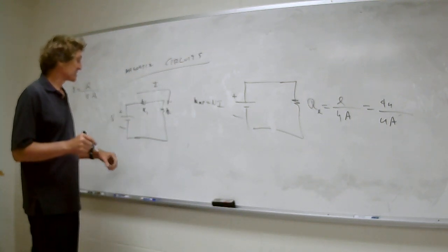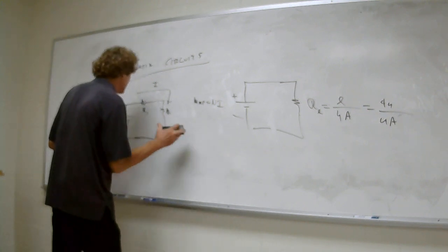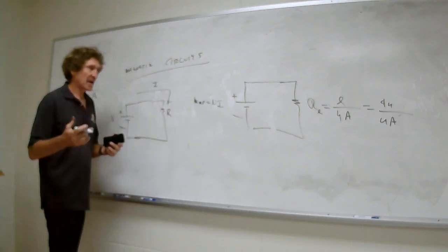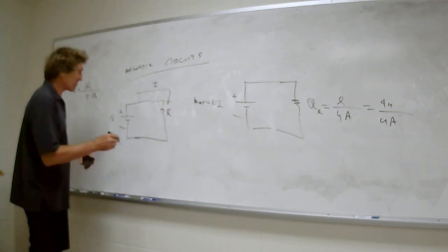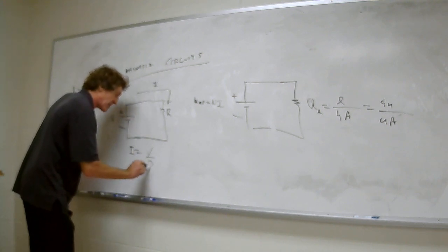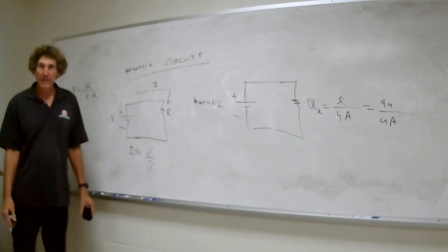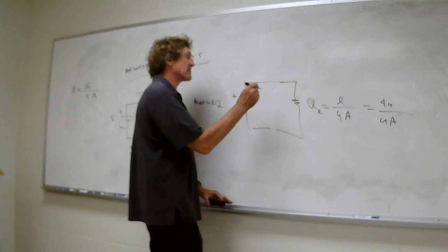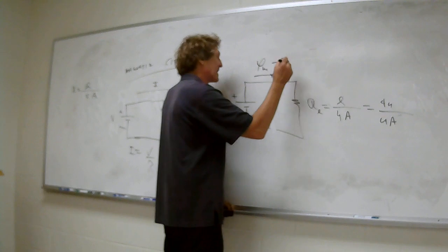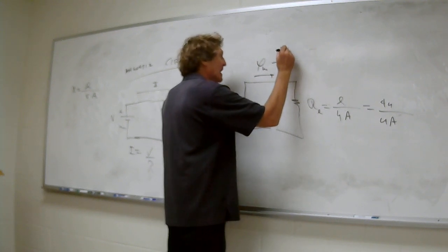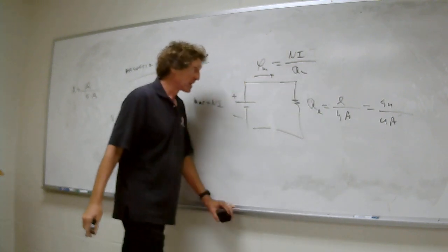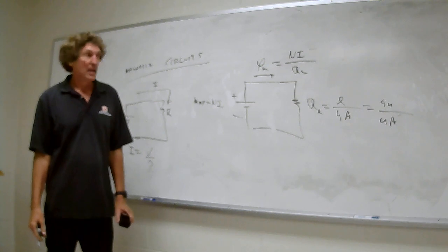It's just like resistance. Here I have two resistors. Maybe I should just have one, like so. And you can see the exact parallels. You all with me? Now over here we have a current I. What is I equal to? Voltage divided by resistance for an electric circuit, right? Well, here we have something akin to current. It's magnetic flux. It's just like current. And it's equal to the MMF, or I'll just put NI, the MMF divided by the reluctance, RL. Can you all follow me on that? That's the reluctance.